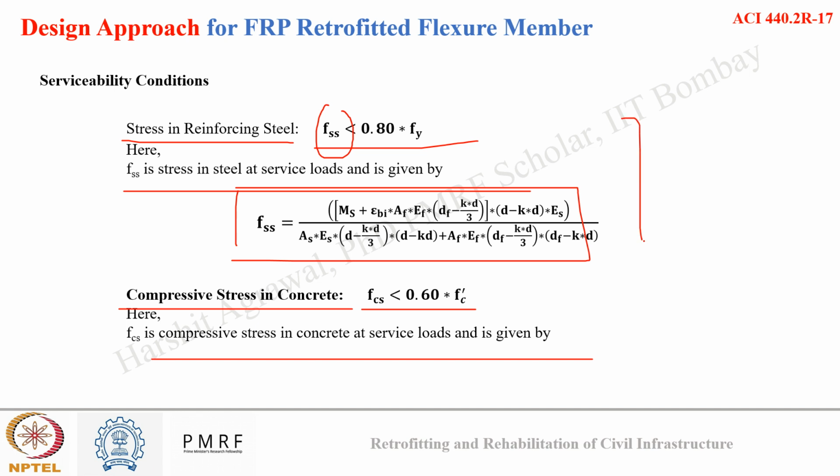Now this is not very major to us because if we opt for IS 456 design criteria, our serviceability condition will be the deflection. That deflection should be less than some value. So that can be done simply as we do in RC design. So we won't give much emphasis to these criteria here. The important thing for us is the design of FRP, the choice of the material, and how that choice of material is able to take the required increment in load.